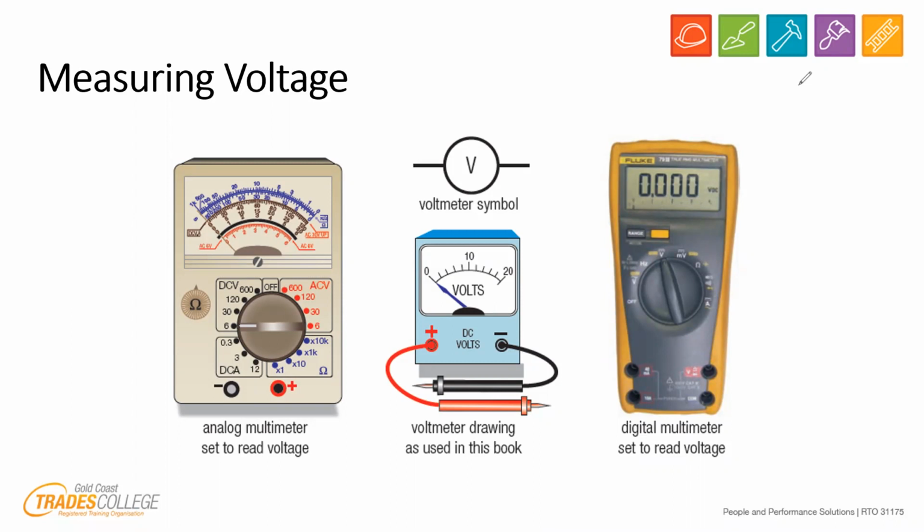All right, later on in the course, guys, we're going to be talking about measuring resistance. That's another test which is super important for fault finding. But for safety, voltage is going to be the one that you guys need to know inside out, back to front. We talked about last week that voltage is the potential difference from one place to the other, the difference in charge, if you like, or difference in electrons from one place to the other. And then we measure in parallel.